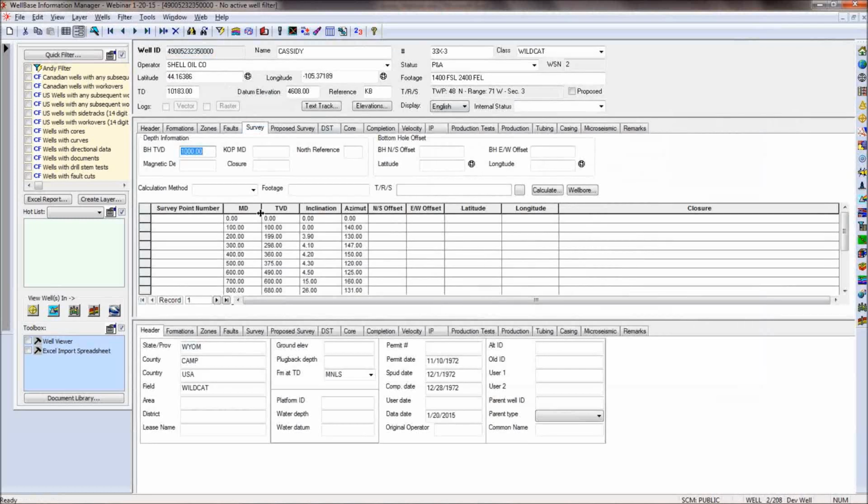Again, this is just the data that I brought over, MD, TVD, inclination, and azimuth. Again, some of your spreadsheets might have additional information. We're just going to calculate some of that additional information. Similar to when we brought in the ASCII file, it did not include, we told it not to calculate our deviation survey, and this is why. We can perform a calculation afterwards.